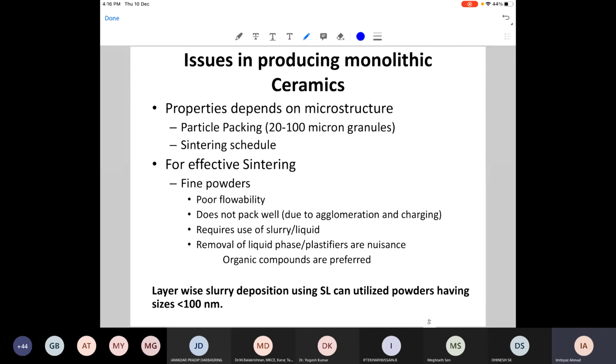Because when you are doing the laser melting or anything, you have the binders in between that have to be removed, and a lot of binder is there, and the powder has to come closer. If you have more than one component, will they be able to fuse with the presence of those pores or the gaps in between? So how effective will it be in terms of producing the microstructure which we need?